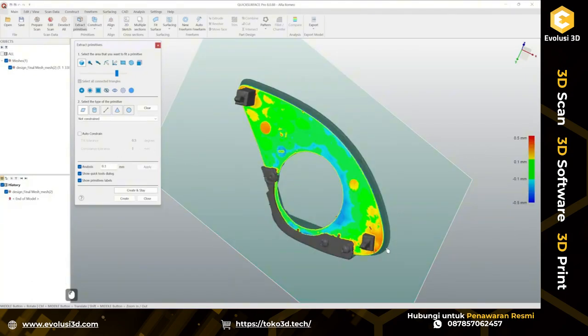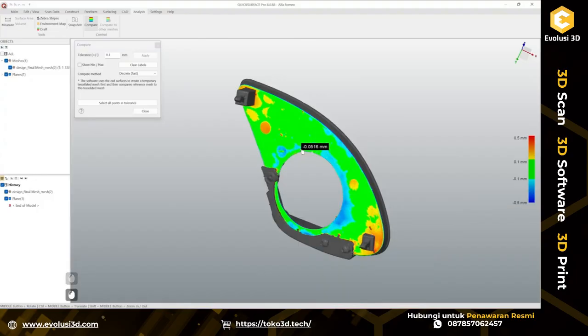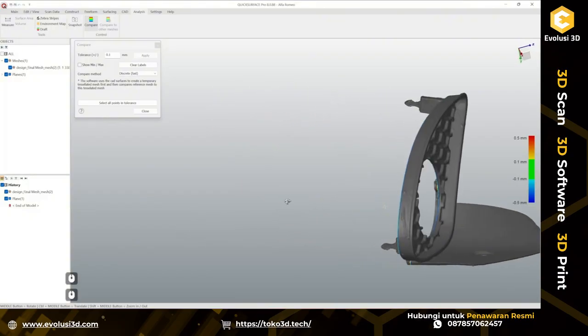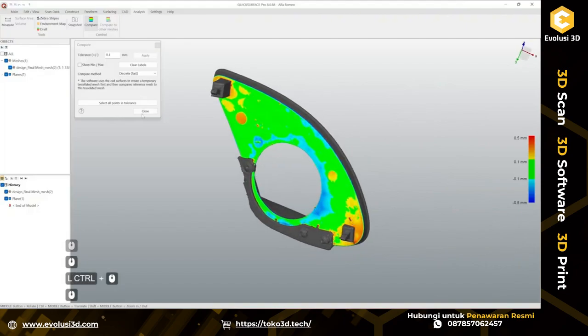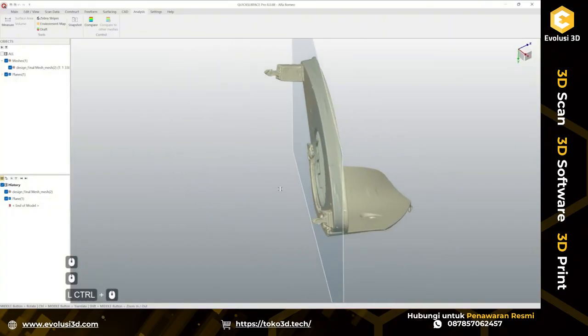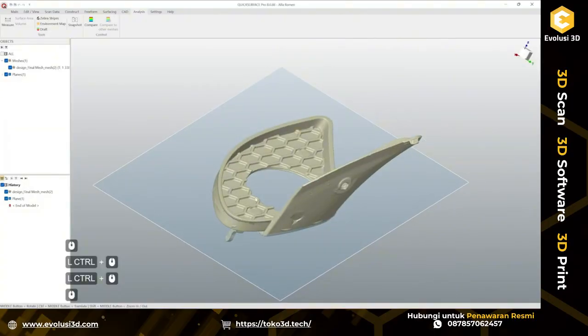So actually here we can see that it has some really slight curvature here, but it's like 0.something millimeters. So most likely this is just a deformation because this part is a used part and has been installed in a bumper, living in the sun and so on. So in this case, like 99.5% this was designed as flat, and that's why I'm going to also design this as a flat surface here.